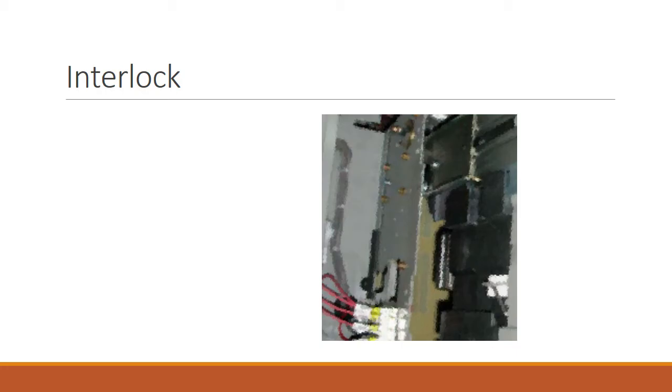Interlocks are installed on switchgear to lock it in the open or closed position, or both in some circumstances. Now, after the switchgear has been actuated, the key is released and the process moves on to the next interlock. The state of the key gives physical verification of the switchgear's working condition, and the interlock mechanisms are simple, durable, and infallible.